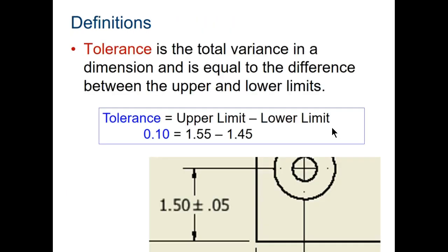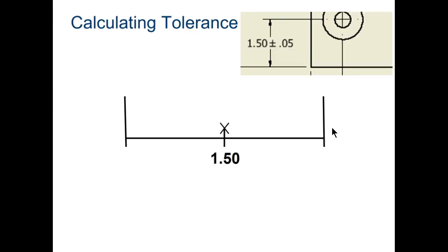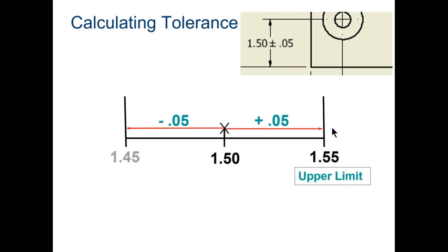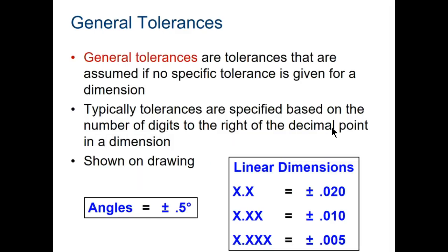And this again is explaining tolerance. To calculate tolerance, you just start with the specified dimension, and then you add and subtract the limits.